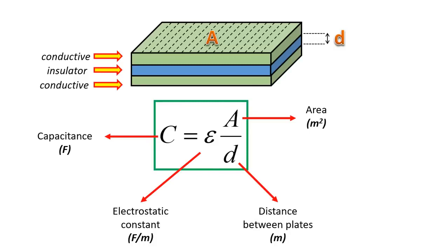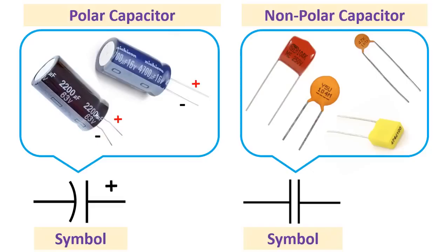The values that you will typically encounter in most capacitors are measured in picofarad, or PF, nanofarad, or NF, and microfarad, or UF. These are often used interchangeably, and it helps to have a conversion chart at hand. Electrolytic capacitors are typically polarized. This means that one pin needs to be connected to the ground side of the circuit, and the other pin must be connected to power. If it is connected backwards, it won't work correctly.